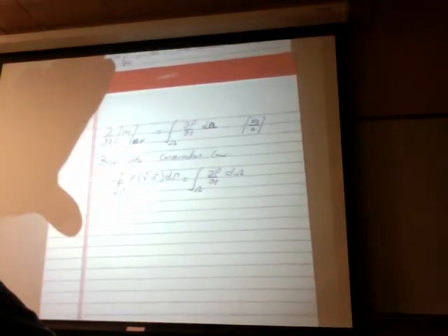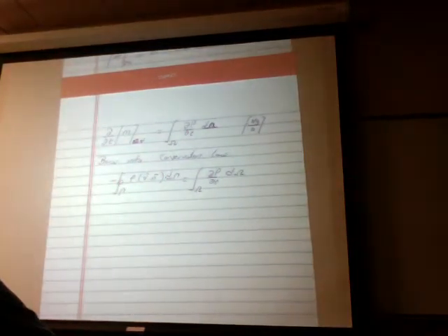The left-hand side is the net amount in or out, and the right-hand side is the amount stored. It's mass storage. Remember, this is a control volume, and a control volume is a fixed window, or a fixed volume. It doesn't change inside.